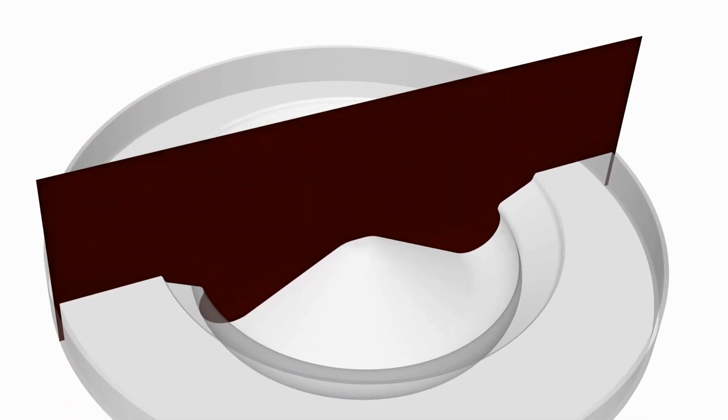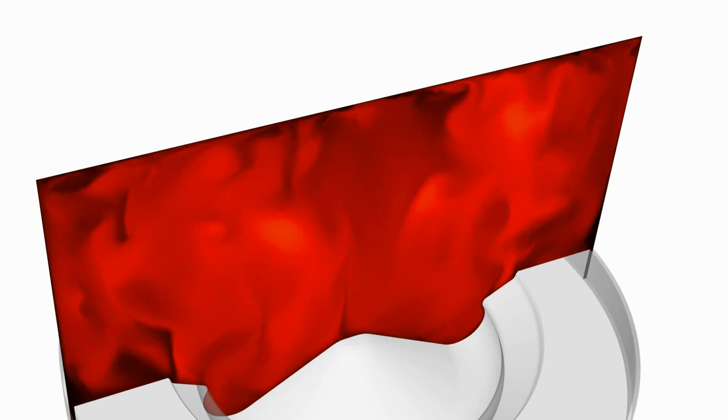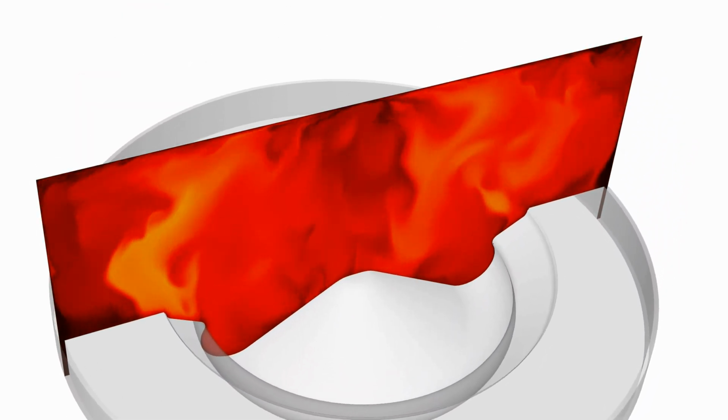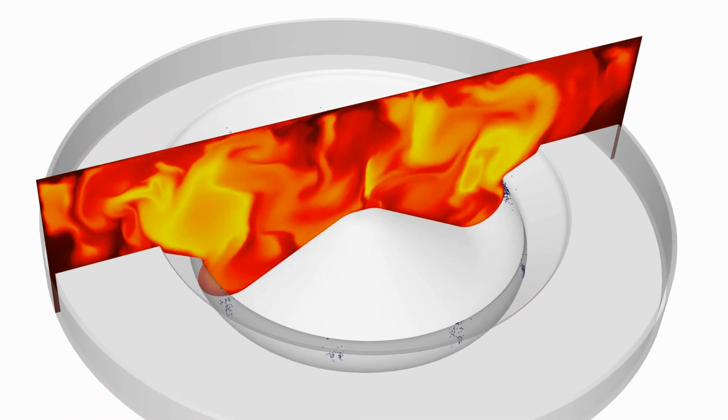CONVERGE is a computational fluid dynamics software with fully coupled autonomous meshing. It has a comprehensive set of physical models that make it ideal for engine simulations, including spray, combustion, emissions, and turbulence models. This simulation being shown here is a high-fidelity LES simulation of a heavy-duty gasoline compression ignition engine run by researchers at Aramco Research Center, Argonne National Laboratory, and Convergent Science.